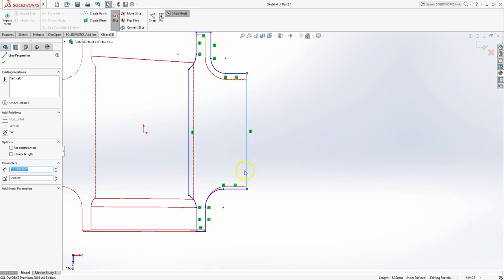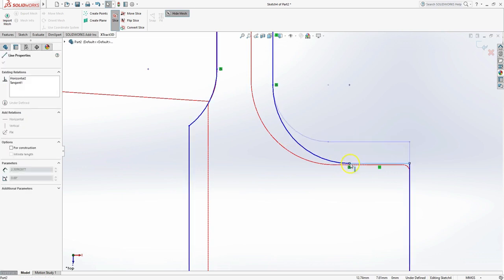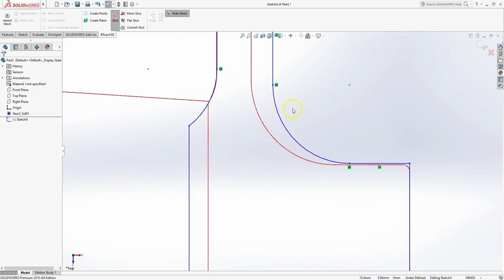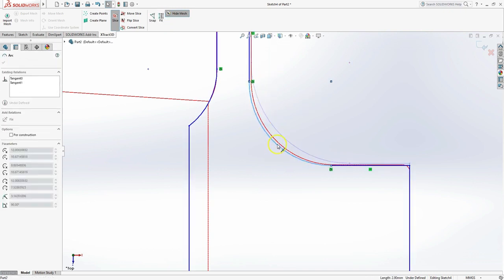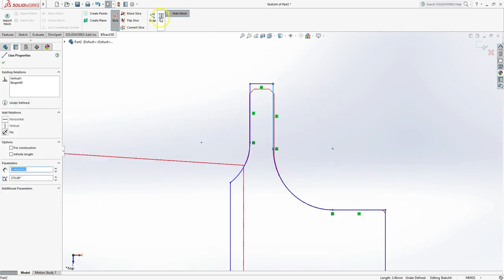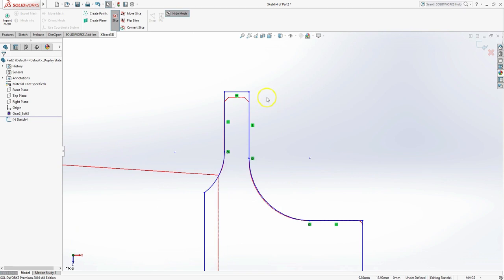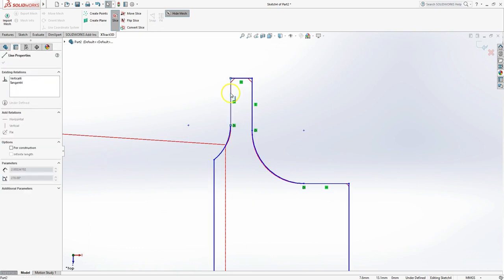It takes that straight line and fits it to the red scan data. We can do the same thing down here. Let's pull this kind of close. We'll do a fit. Get that close. Fit. And then pull this over here. Pull this down like that, and get that one to fit. Just like that. So that's a nice little feature that allows you to get pretty close, but if you want some confidence, just hit it like that.